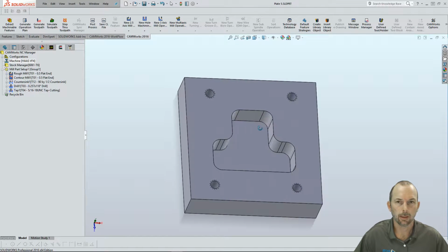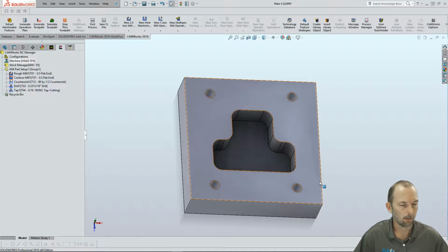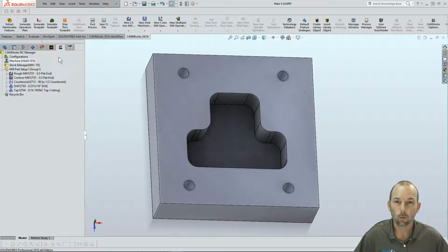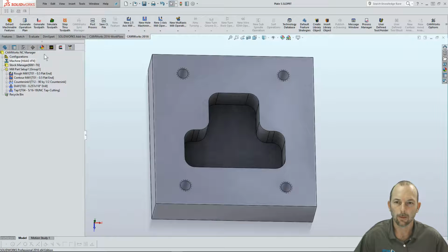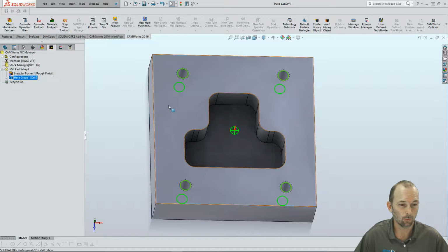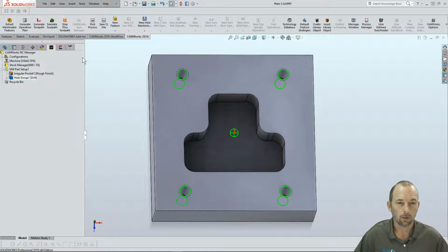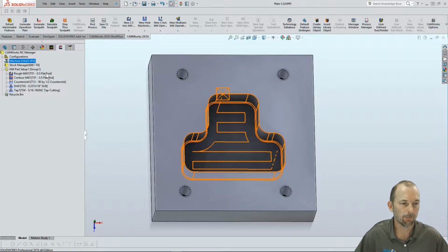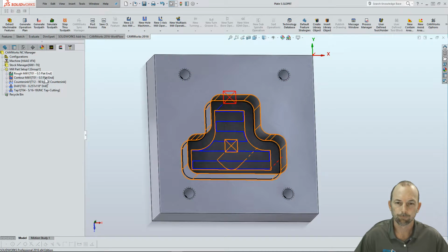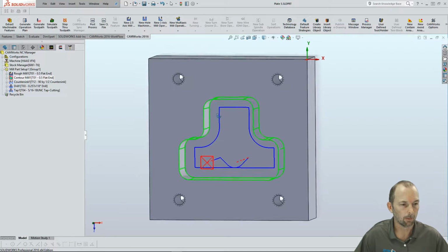Now, as I said, SolidWorks is the CAD tool that we use to create our model, and then we use CamWorks, which is a plug-in into SolidWorks, in order to generate the tool paths. We created a pocket, and then we did a rough and a finishing from that pocket, and then we created a hole group in order to program our holes. In the operations, we used a 1/2 inch flat end mill, did a zigzag pattern to clear the material, and then we just did a profile.